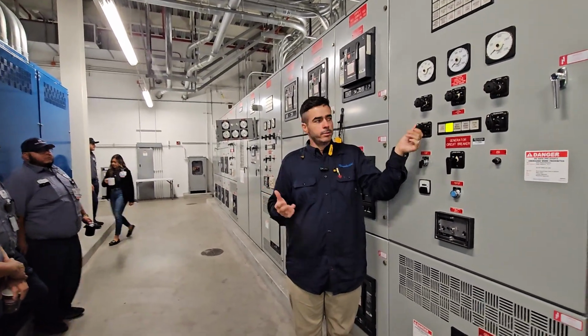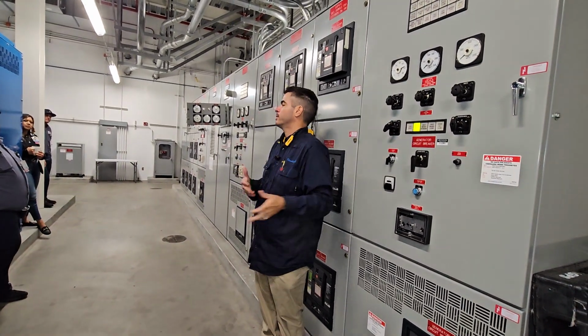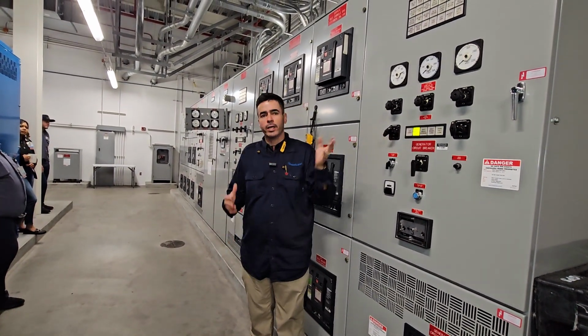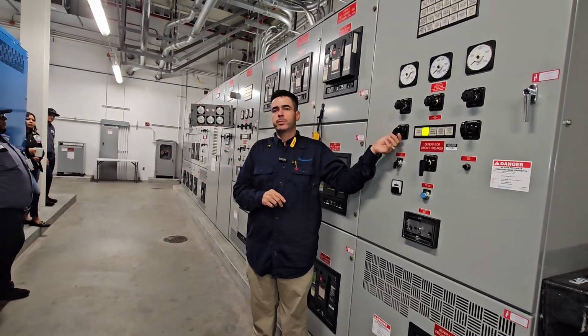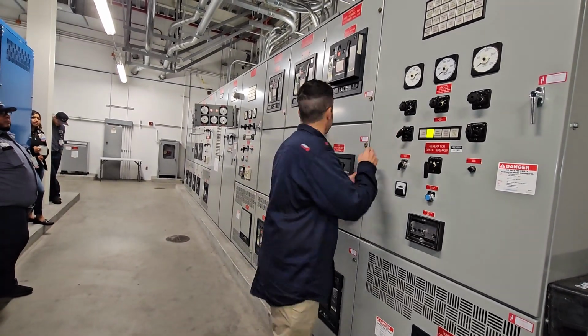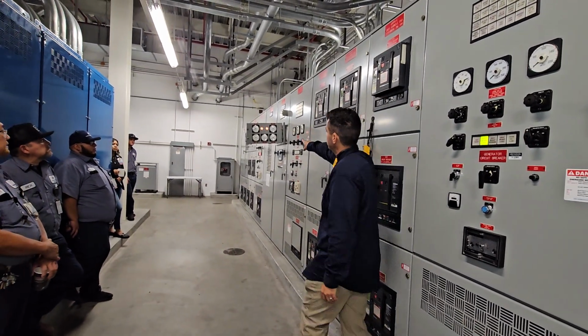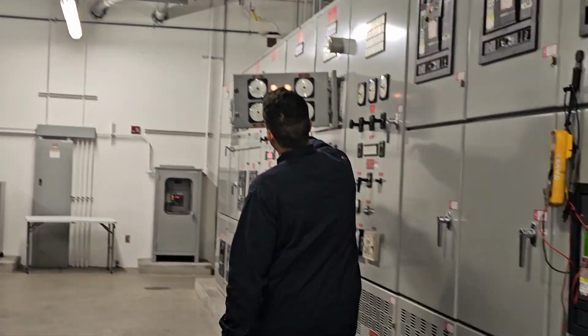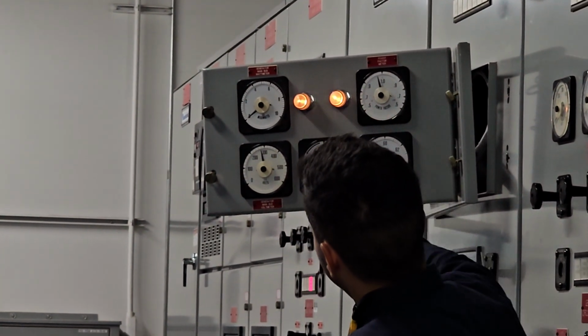One thing that I gotta do is turn this key on. If I don't have that key because I forgot it over there, then I can't do anything. That's why we add that condition. Only one key for all the generators, and you have to turn it on. Now when I turn it on, check the synchronoscope and the lights. The synchronoscope is going away from 12 o'clock, and the lights are getting brighter.